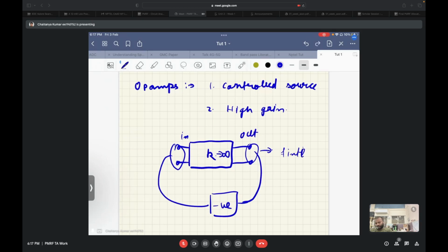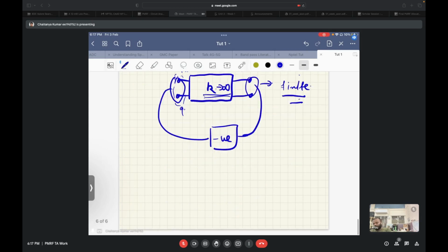So this value will be something finite. Now any finite voltage or current, when divided by an infinite gain, gives an input terminal quantity that is zero. So the bottom line is that if an op amp with a very high gain is connected in negative feedback, the controlling terminal of that op amp will go to zero. The controlling quantity of that op amp will go to zero.